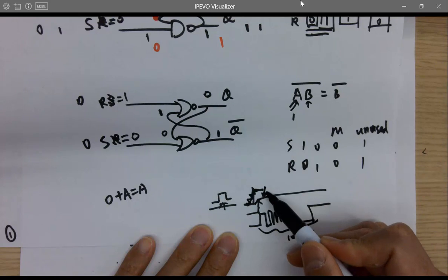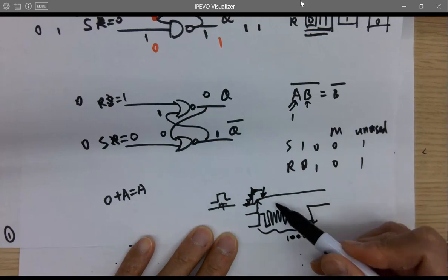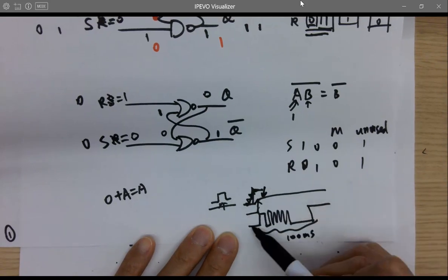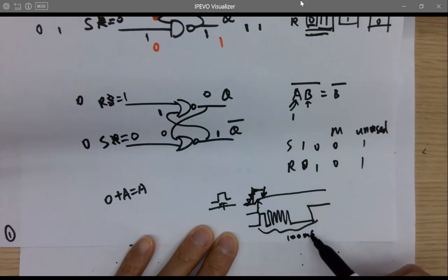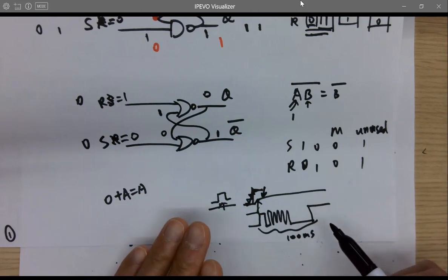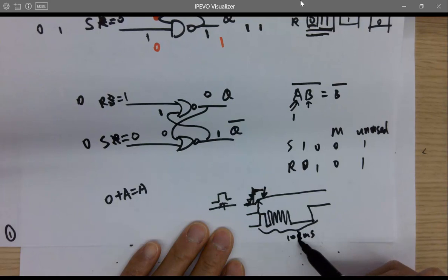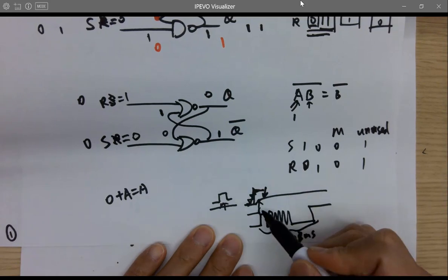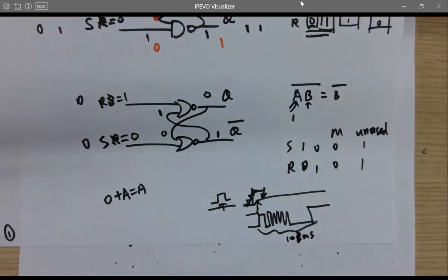If the logic is high, I'm going to do this, all right? However, it's like this, really fast in the very beginning. Maybe 10 milliseconds, let's make it shorter. But the software can run really fast because your Arduino is running at 16 megahertz. So the software runs a loop within like microsecond level.